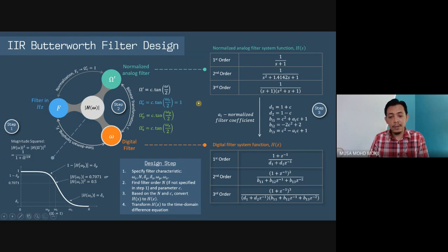If it is an FIR filter, you can have either a difference equation or an impulse response, because when you have an impulse response, you can do convolution, the normal convolution. For an IIR filter, practically you cannot do the convolution because it will give you an infinite summation. Not possible, not practical.